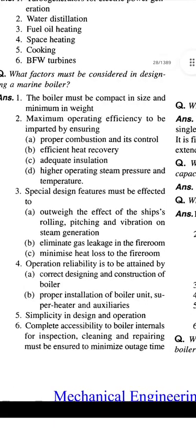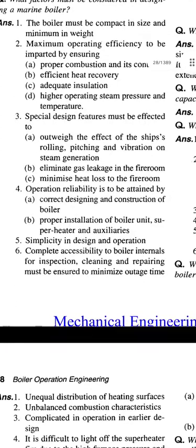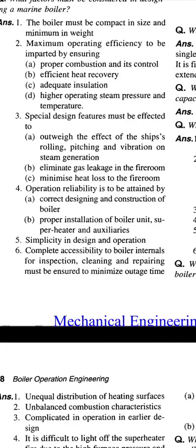Third, special design features must be incorporated to outweigh the effect of the ship's rolling, pitching, and the vibration on the steam generation. Eliminate gas leakage in the fire room. Minimize heat loss to the fire room.